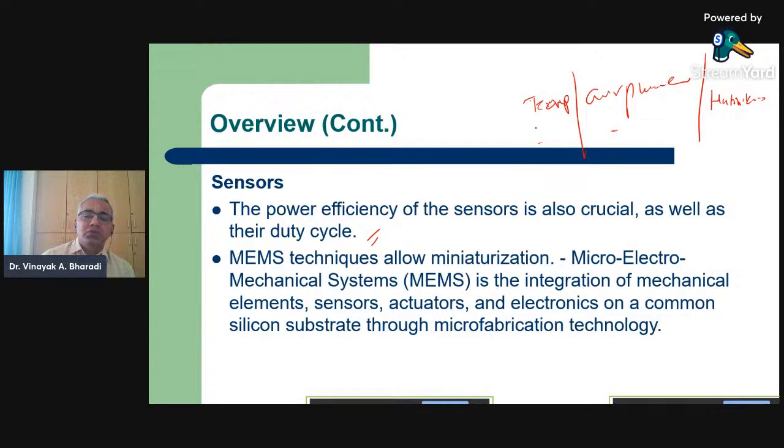Here, the thermoelectric effect can be used in temperature sensing. For air pressure, we need to use a microelectromechanical system, where the change in the air pressure has to be reflected in some mechanical system. And for humidity, the conductivity between two electrodes changes if there is humid soil or moisture. Current is increased when humidity is more, and current is decreased when humidity is less. This phenomenon is used for sensing purposes.